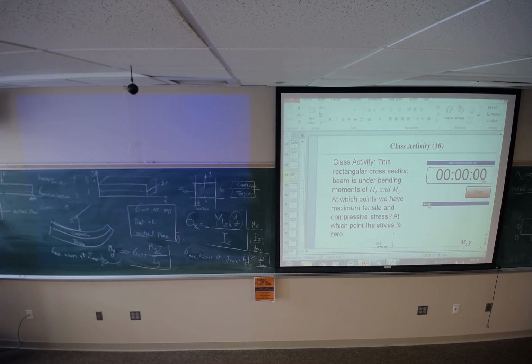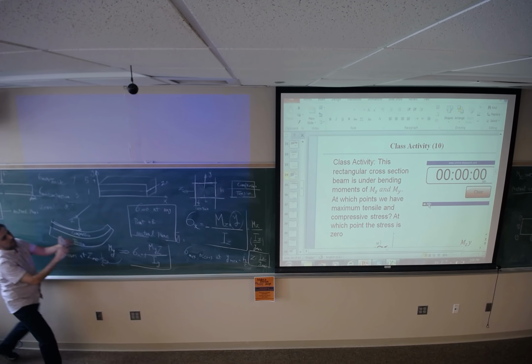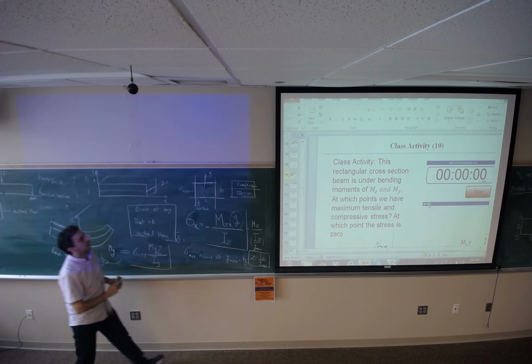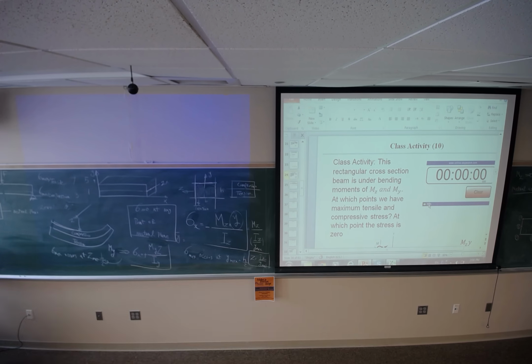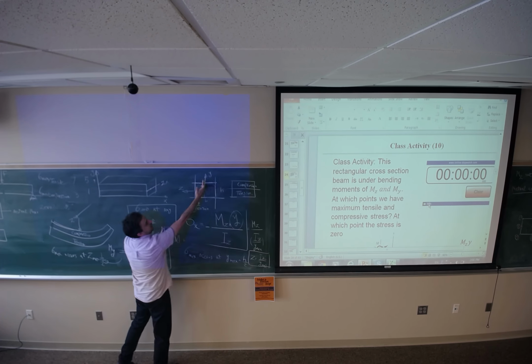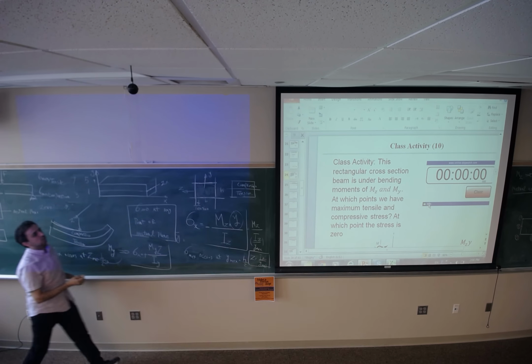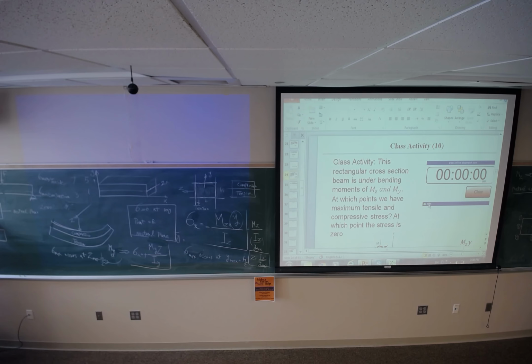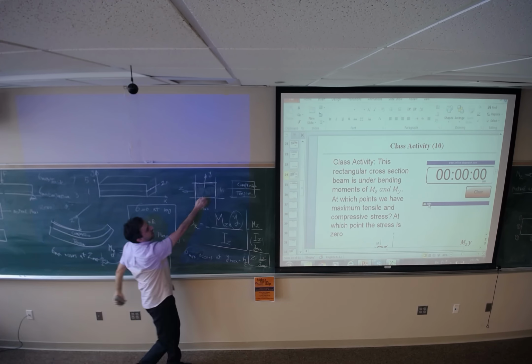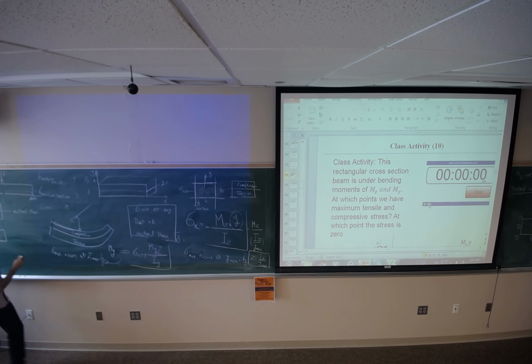And here we are going to see the tensile, if we bend in the Z direction. Now, if I bend in the Y direction, just positive Y, this is going to represent the neutral plane, which is at the middle. The right side is going to see compression, and the left side is going to see tensile.